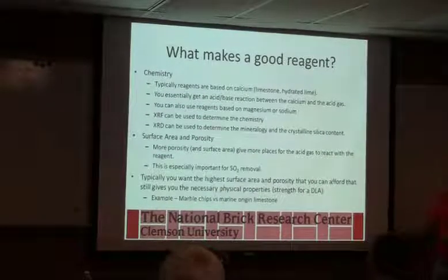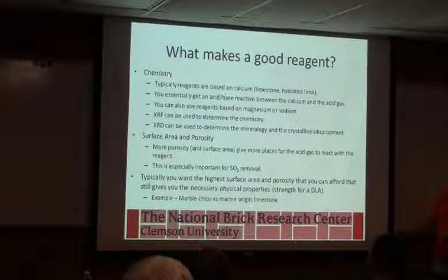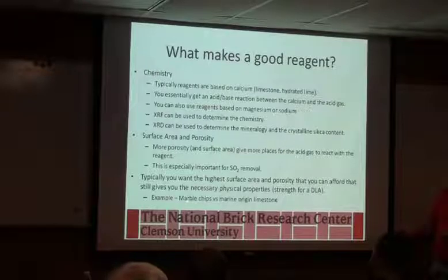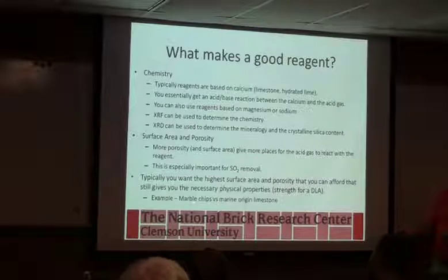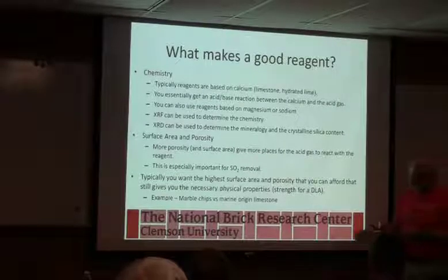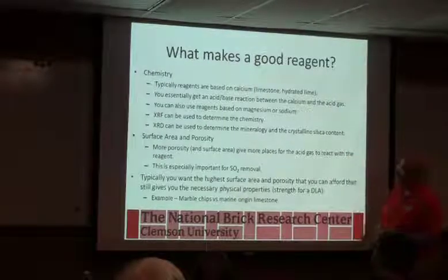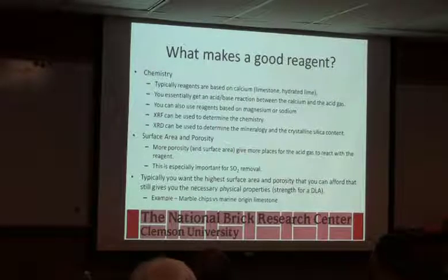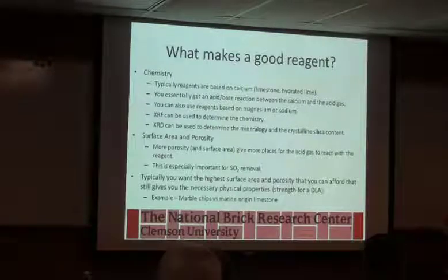So this is an example I was telling you. We had a place that was using the marine limestone, we call it. Their vendor said, oh, I got this better limestone, it's great stuff, you need to try it. They had a stack test and they were way over their limits. We started looking and this stuff just wasn't reacting that well. It was too dense. So they had to go back to the marine origin and do another stack test, and they weren't real happy about that. So there are some easy tests you can do on the porosity or density and the chemistry to make sure you've got what you're supposed to have.